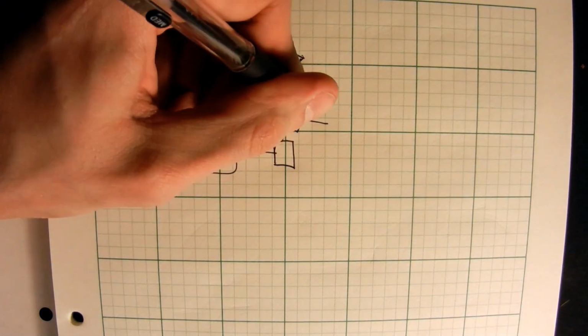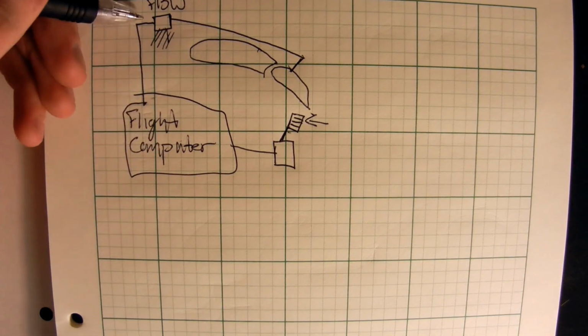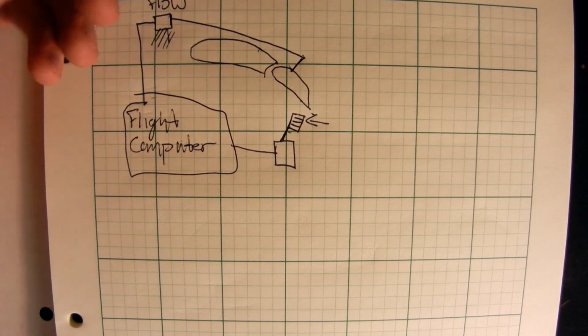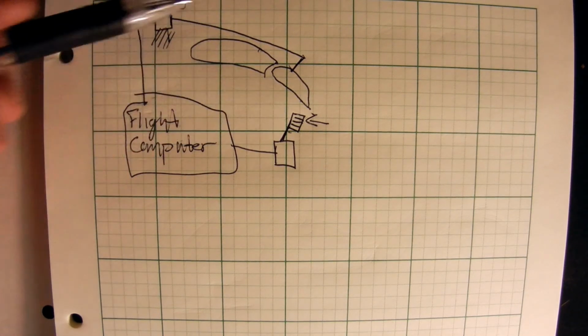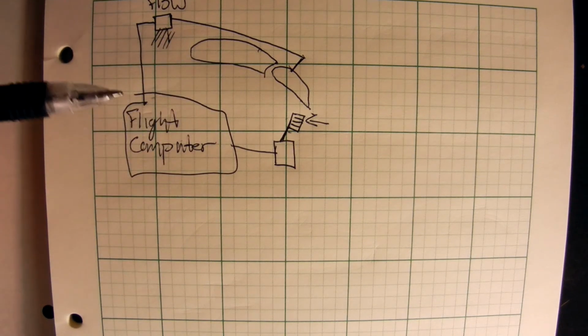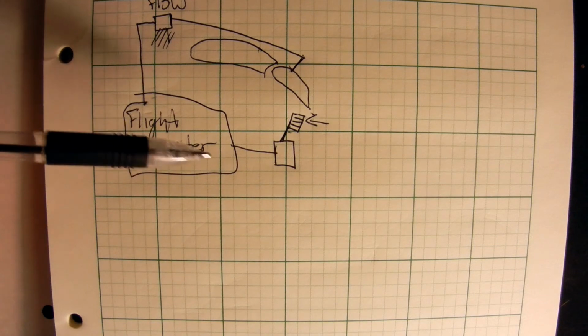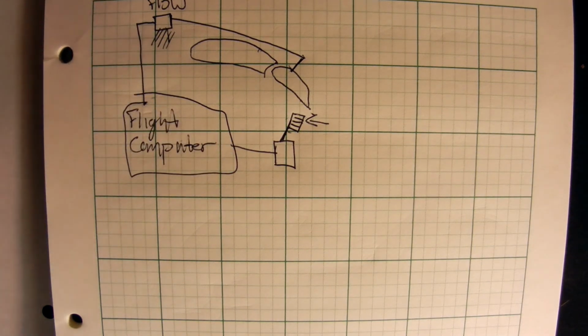So when the pilot pushes this, it sends a signal to the flight computer, and then the flight computer will in turn move this. The flight computer also looks at what the pilot says, and it's going to double check to make sure: what the pilot's telling the plane to do, is that actually able to happen? If not, it won't do that, even though the pilot says do that. It won't do that unless it knows the plane can, because it knows exactly what the plane is limited to from the equations of motion and experimental data.